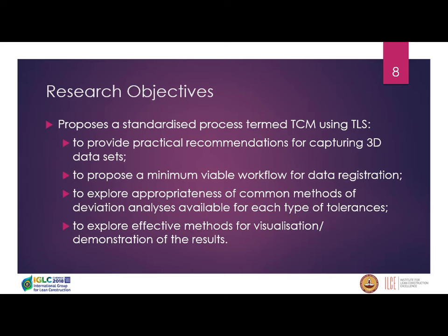And also, when you want to register data, as I said, registration means how you are going to put the scans next to each other. For that, you need to have a workflow. I've spoken to many operators who use laser scanning, and each of them has his or her own workflow. We propose a workflow that we call a minimum viable workflow for data registration. It ensures that your data registration is to a high level of accuracy.